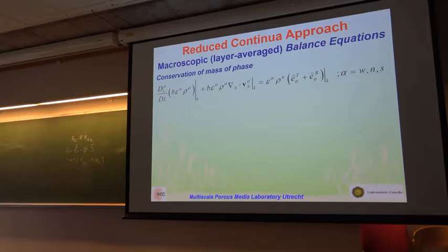Okay, I'm not sure we can talk about this, but to me, over the thickness, I have 10 pores. It has a volume. My REV has a lateral dimension, so I have a volume of water there. Then I say, okay, the concentration of salt is the mass of salt in that volume divided by the volume of water. It's a very well defined concept. And in fact, that's how I measure it. We use TDRs here to measure water saturation.